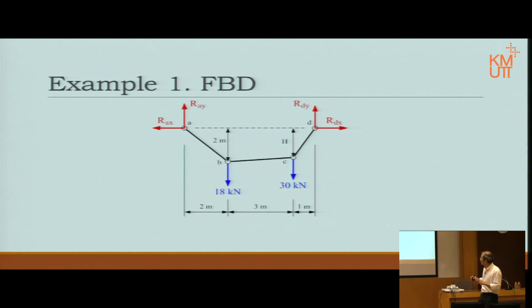Now, at this moment in time, we have one free body diagram. Then we have three equations, correct? The three equations of equilibrium: sigma Fx equal to 0, the summation of all forces in the y direction, sigma Fy equal to 0, and the summation of all moments about any point equal to 0, or sigma M equal to 0. Three equations, but we have four unknowns, right?